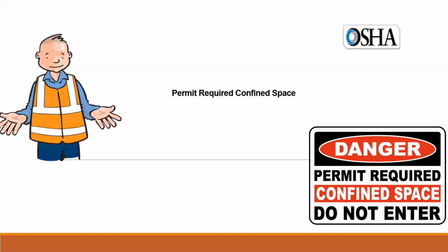Similarly, you can have a blanket permit if you want to use it for more than 8 hours, but in this case again a thorough inspection will be carried out, and then you will have the same permit continuation. But normally what we have seen is that one permit cannot be issued for more than 24 hours. So after 24 hours, you have to get a new permit issued.